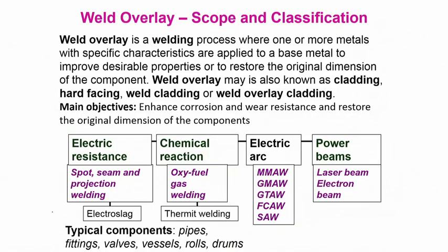We also discussed diffusion coating, where actually not interstitial atoms, but substitutional atoms, bigger ones like aluminum or chromium or silicon or any of these elements could enter into the surfaces of the metallic substrate and then create solid solution, and at the same time certain intermetallic phases, and in the process they offer resistance to high temperature oxidation particularly, and also other kinds of surface degradations. Now we are going to discuss weld overlay, which is